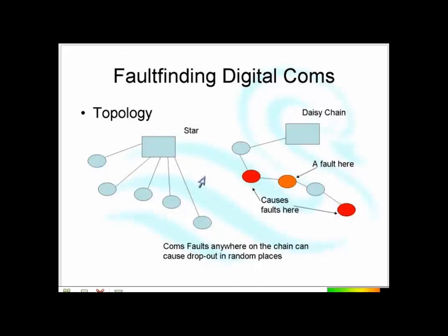With modern systems, you don't need to send a cable to each instrument. What you do is you send one cable from the control room out to the first instrument, and then you just wire from that to the second instrument, from that to the third, to the fourth, to the fifth, all the way down the line, until you'd be wiring to, say, this instrument over here, which might be instrument number 125, for instance.